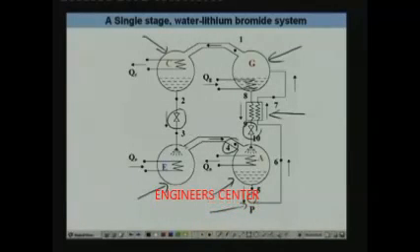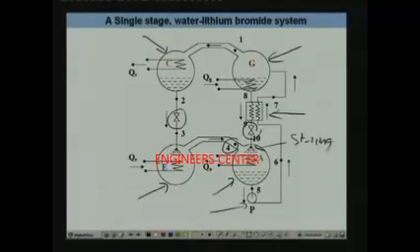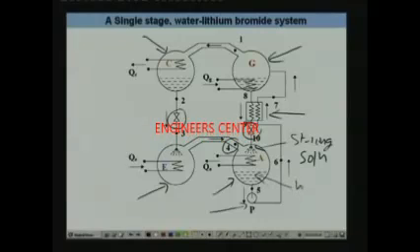At the exit of the evaporator, as you know, you have low pressure, low temperature refrigerant vapor. This low pressure, low temperature refrigerant vapor enters into the absorber, where it comes in contact with the strong solution that is coming from the generator. Since this strong solution has affinity for the water, the vapor gets absorbed here. And what forms here is a weak solution or a dilute solution.